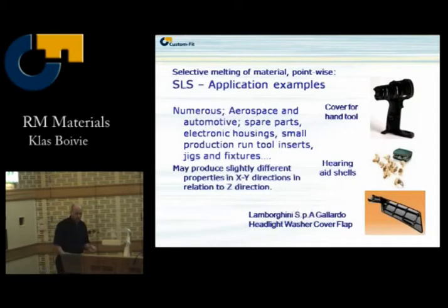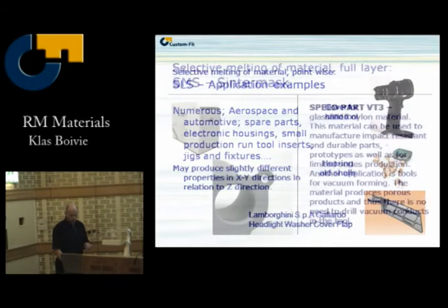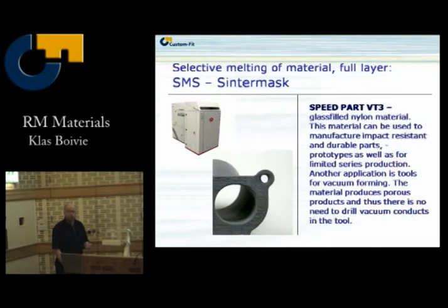You can have different material properties in the X-Y direction in relation to the Z direction due to the orientation, the scanning orientation, how you orient the part in the build. It's worth having a look at when you try new things. Sinter mask, David talked about earlier.